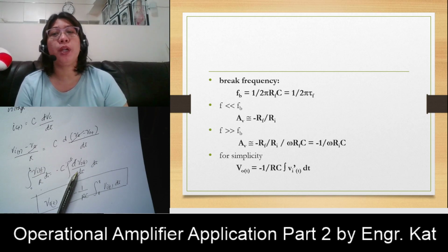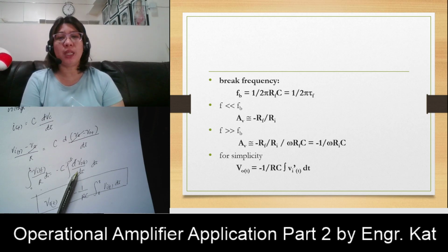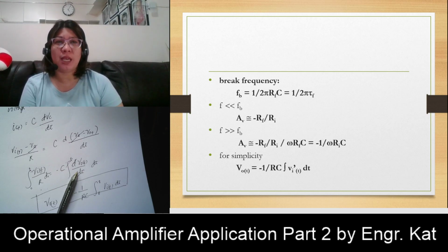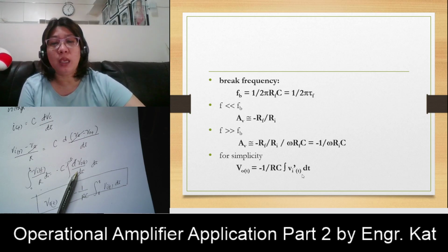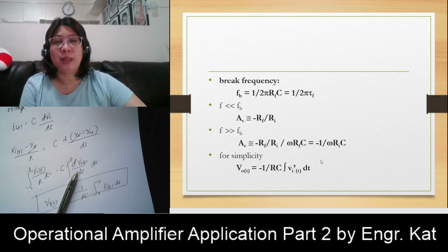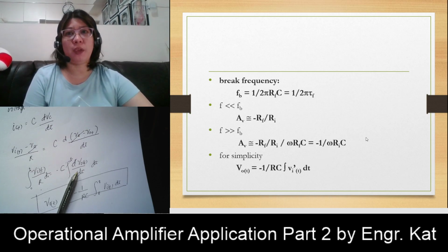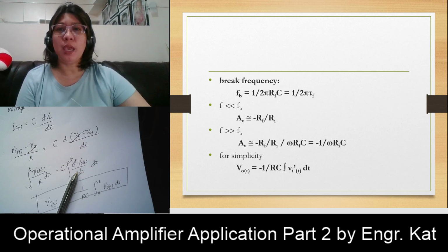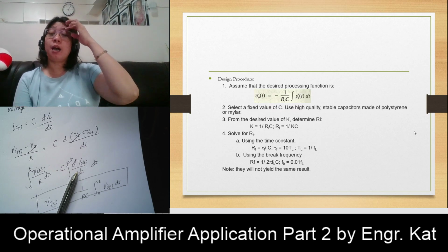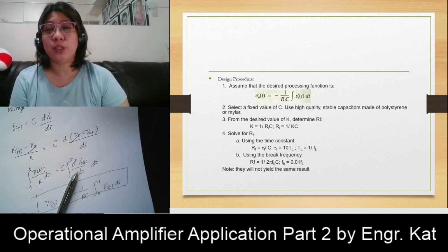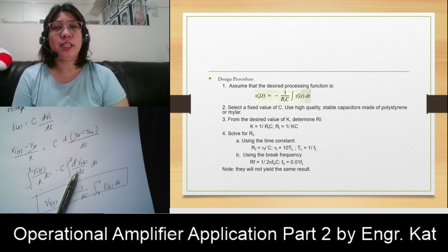However, when your input frequency is greater than your break frequency, that is the time when your operational amplifier is functioning as an integrator circuit. For simplicity, other books and references use a prime here. When you see a prime, that means we are using an AC integrator instead of a true integrator circuit.